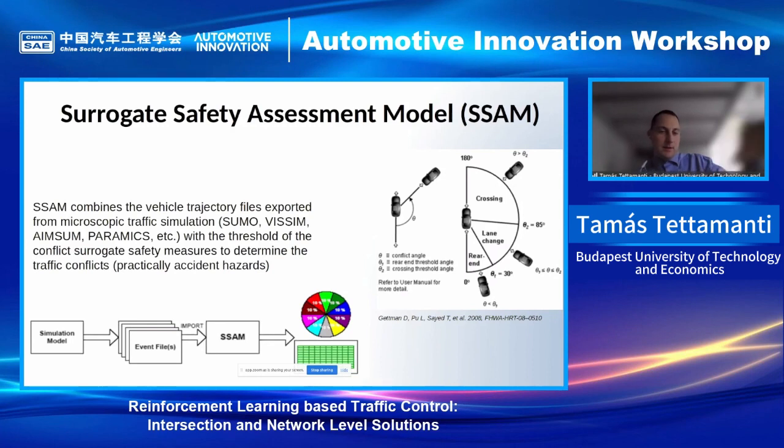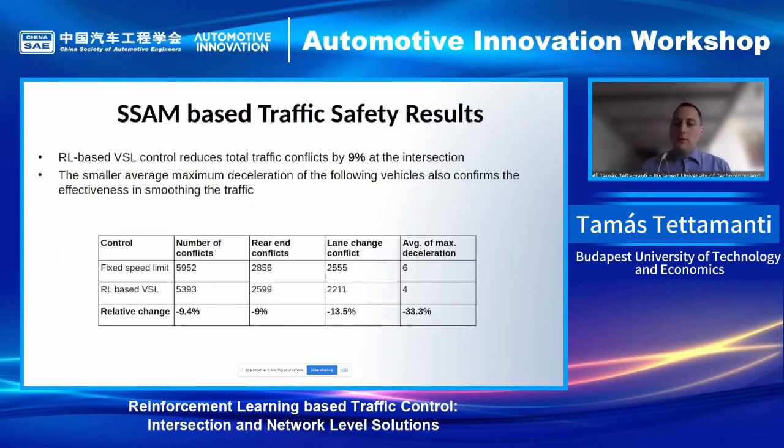And please note that in SUMO or VSIM or other microscopic traffic simulators, we cannot model accidents because they are not accident simulators, of course, but we can analyze different thresholds and different parameters of each car based on the trajectories, and that can be very useful to analyze the traffic system in terms of safety. And a few results you can see here.